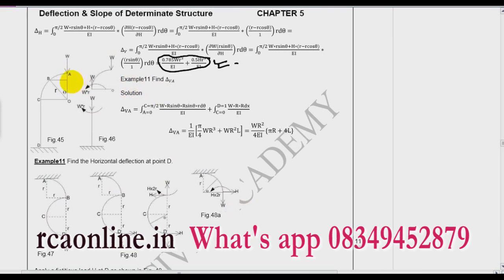Let us take a combination of linear and curved member. So this is my curved member and this is my linear member. CD is my linear member. So what will I do? I will use the free body diagram concept. What is the free body diagram concept? The section here I can divide into two parts. One is the upward W and anticlockwise WR. Similarly, downward W and clockwise WR. Now for this part, if I need to find the vertical deflection, then what do I have to do?